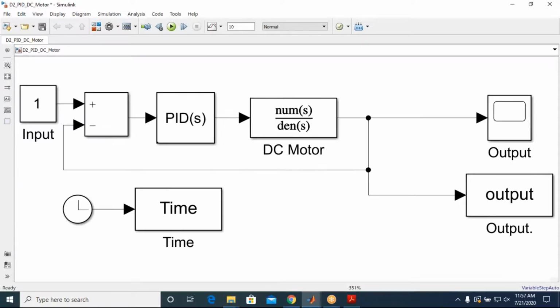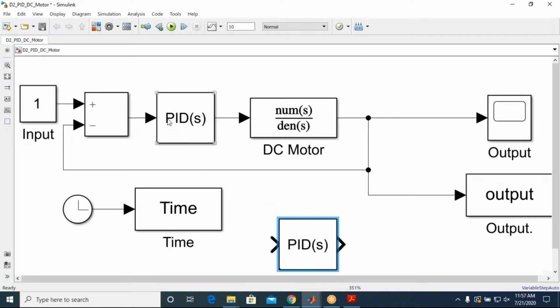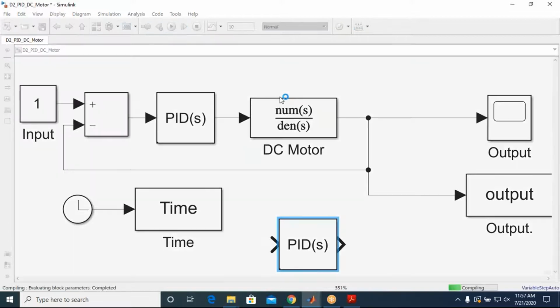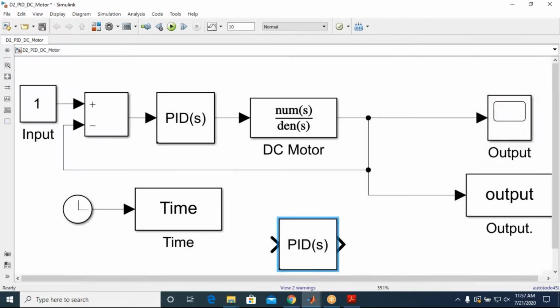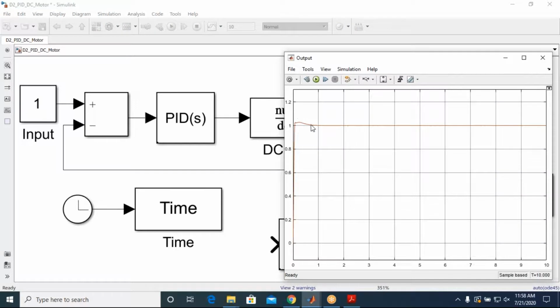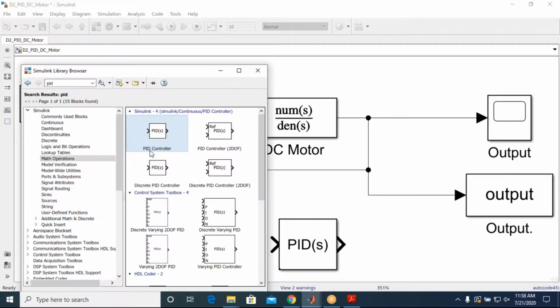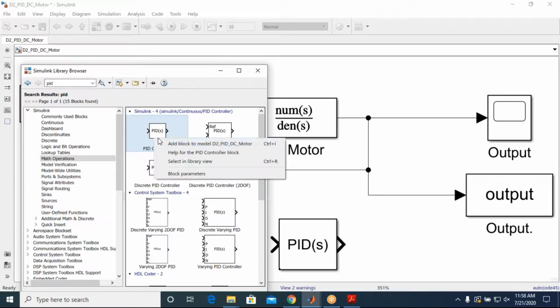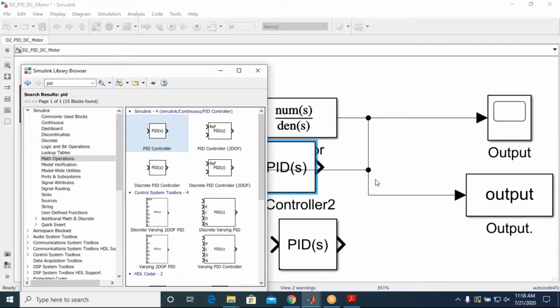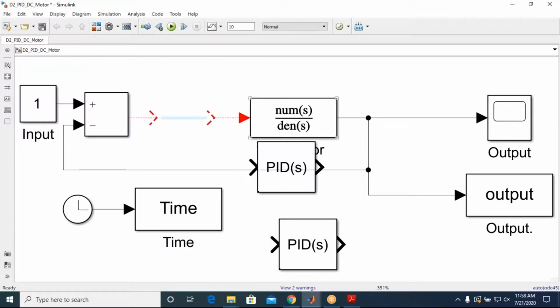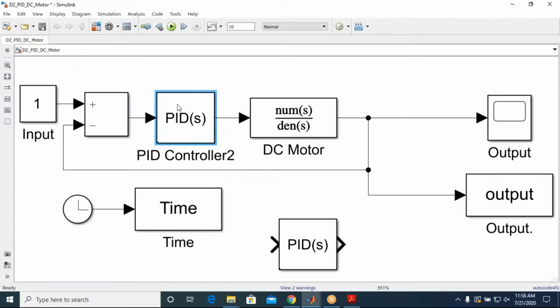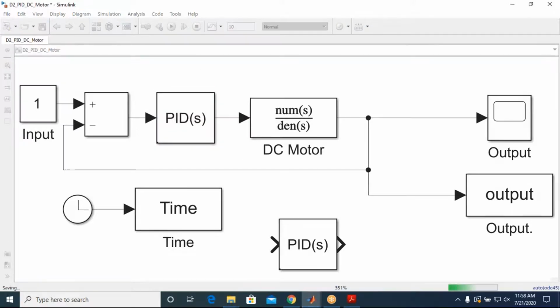Okay. So now how do you get these PID values? The first thing is to get this PID. I will keep it aside. I will not do anything, but just run this one and show you how it is working fine. You can see the same response you saw there. But how to do it from scratch? Just go here, use the new PID, the standard add PID block, and remove the one which I have designed. You click this one, and now from here the actual design starts.